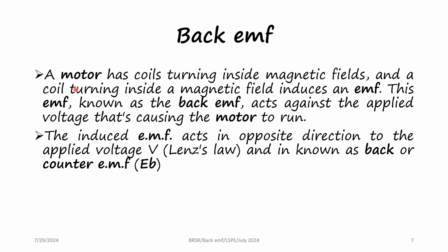So back EMF is defined like this. A motor has coils turning inside magnetic fields and a coil turning inside a magnetic field induces an EMF. This EMF is known as back EMF and it acts against the applied voltage that is causing the motor to run. Induced EMF acts in the opposite direction to the applied voltage as per Lenz's law, and that is known as back EMF or counter EMF.